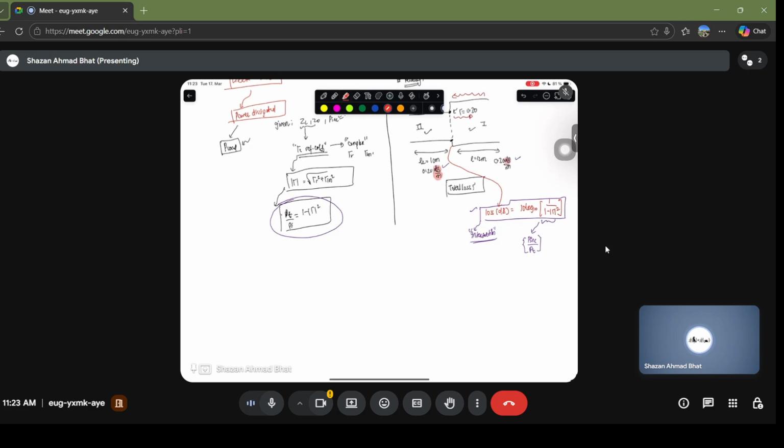But one thing that you need to consider here, the important thing, is that this is in decibel per meter, this is in decibel per meter, so you need to multiply it with the length. So when you compute the total loss, that will be 0.20 decibel per meter multiplied by its length, which is 10 meters, so that the meter and meter will go, everything will be in decibels. Similarly, plus 0.30 decibel per meter multiplied with its length, which is 12 meters.